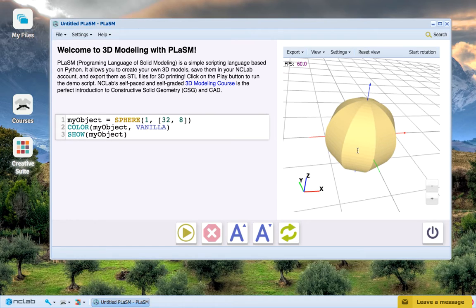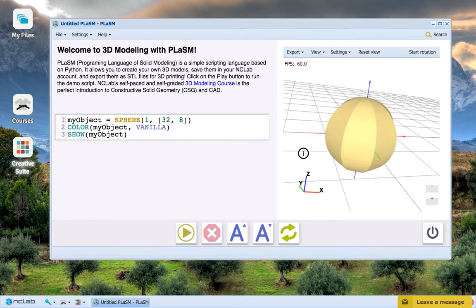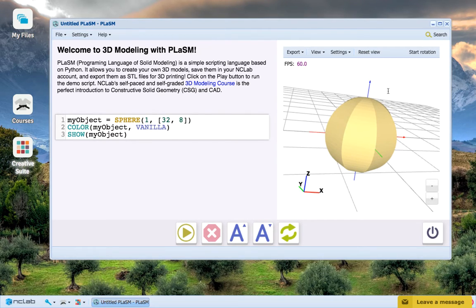The sphere command takes a second parameter, which is a 2-item list, which controls the numbers of these lines directly. The first item controls the number of meridian division lines, which run horizontally and divide the meridians. The second item controls the number of equator dividing lines, or the actual number of meridians. By adjusting these, you can make your sphere smoother and create a wide variety of interesting 3D figures. Try adjusting the numbers in the second parameter list and see what kind of figures you can make.